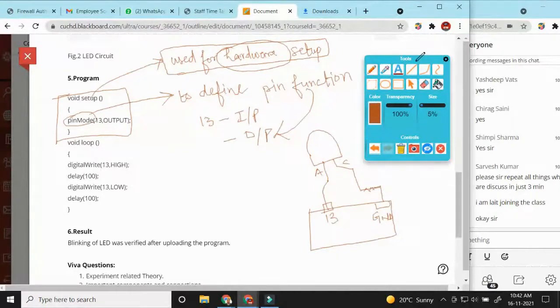After that, to glow this particular LED, our task is to turn this LED on and off. Okay, and continuously this operation should be performed, so that we can see the blinking of this LED continuously. For that we have to create a loop. Initially we will set this LED to on, and then we are going to place some delay. Okay, so what is delay?